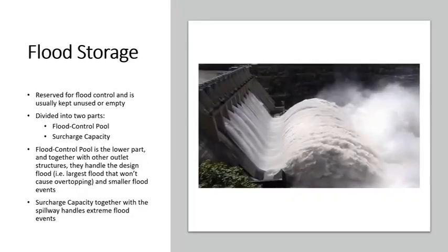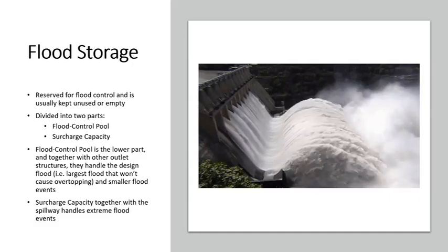And finally, the flood storage component is actually mostly empty unless you have a flood. Flood storage is divided into two parts. First is the flood control pool, and second is the surcharge capacity. The flood control pool is the lower part, and together with the lower outlet, they handle the design flood, or the largest floods that won't cause overtopping, and other smaller flood events.